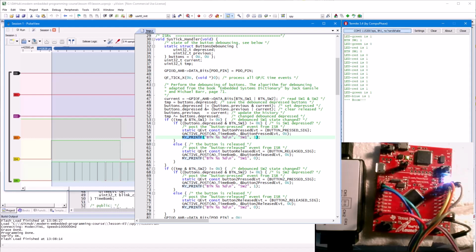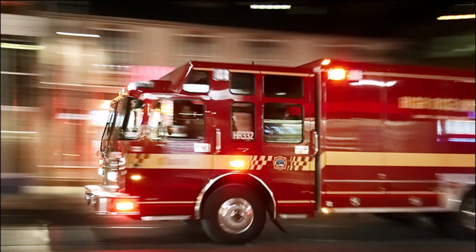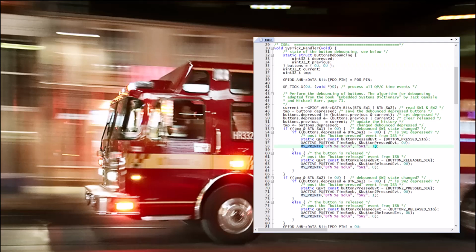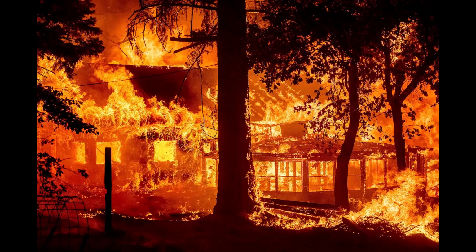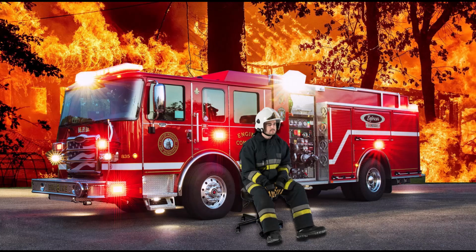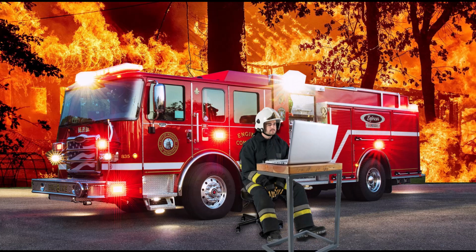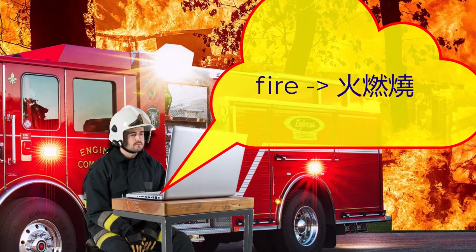to go about it. The main problem is that this approach combines the production of the tracing data and sending it out over UART, the ITM, or some other mechanism, which is very time-consuming. To help you realize what's happening here, imagine a fire truck racing to an emergency. This would correspond to your time-critical path through the code. But instead of fighting the blaze and rescuing the victims, the fireman starts filing a situation report to his boss, which takes him an hour. This is what software tracing is and how a millisecond feels to a modern CPU.